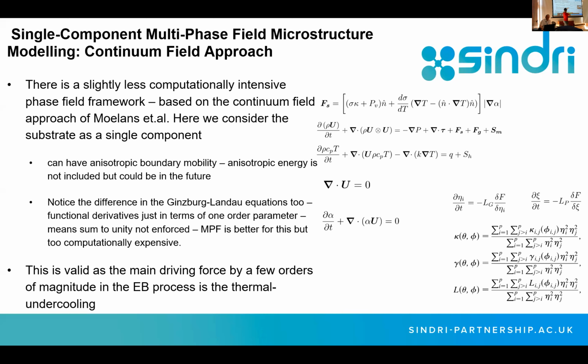It's fully coupled to the momentum transport, energy conservation, and it's actually coupled to a volume of fluid type approach as well. The reason this isn't such a nice treatment is that you need a semi-analytical solution to get the anisotropic dependence on the energy in this approach. So that's why it's maybe not as elegant, I don't think.